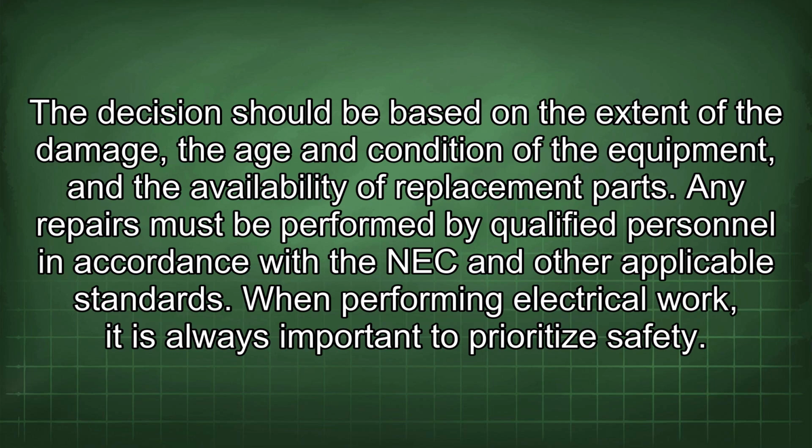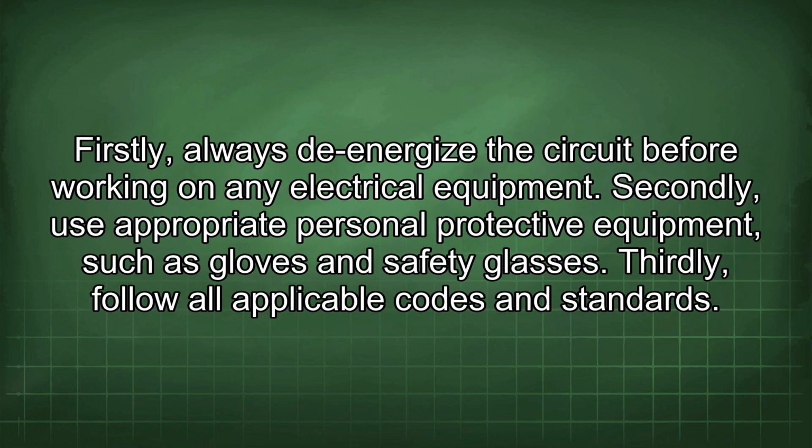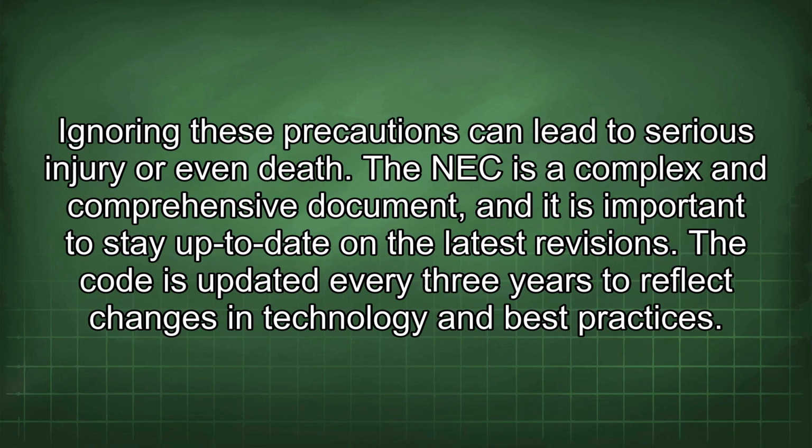When performing electrical work, it is always important to prioritize safety. Firstly, always de-energize the circuit before working on any electrical equipment. Secondly, use appropriate personal protective equipment, such as gloves and safety glasses. Thirdly, follow all applicable codes and standards. Ignoring these precautions can lead to serious injury or even death.